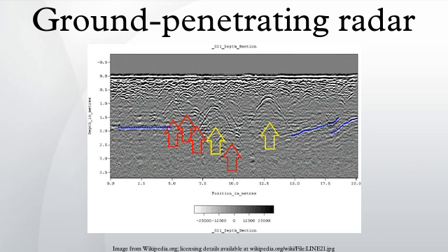GPR can be a powerful tool in favorable conditions. Like other geophysical methods used in archaeology, it can locate artifacts and map features without any risk of damaging them. Among methods used in archaeological geophysics, it is unique both in its ability to detect some small objects at relatively great depths, and in its ability to distinguish the depth of anomaly sources.